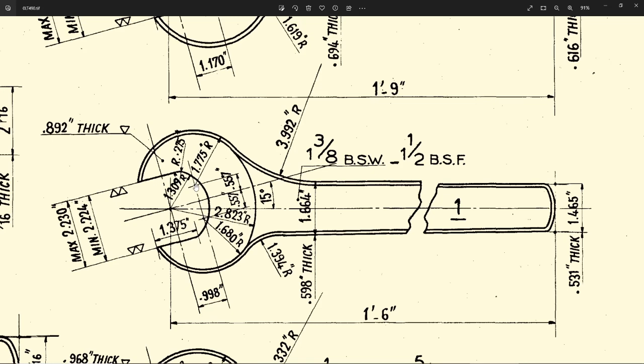If we have this line set here, the endpoint of this arc is on it at the endpoint, and its value is known, and this width is known about this center, this is over defining it. So I'm not going to address this. This would have been the A value. I'm going to leave this undefined and define it by this radius, because it uses that radius and these to figure out our chamfer. So I'm just going to let the system solve for this because we're over constrained.